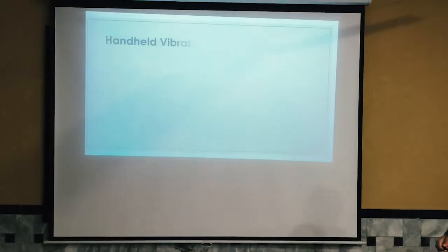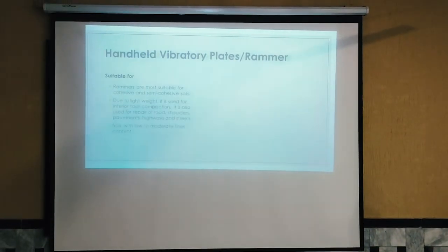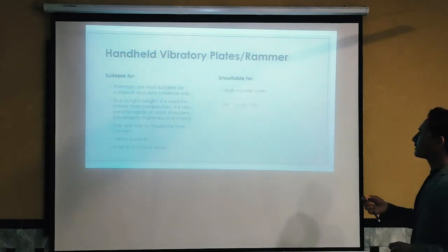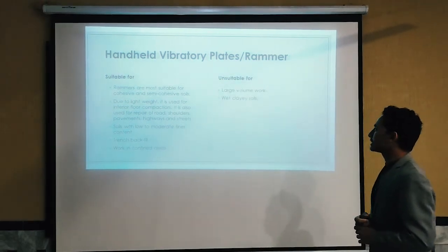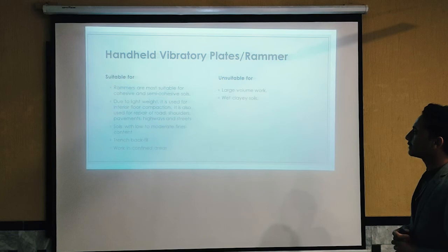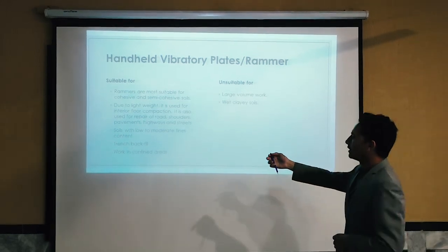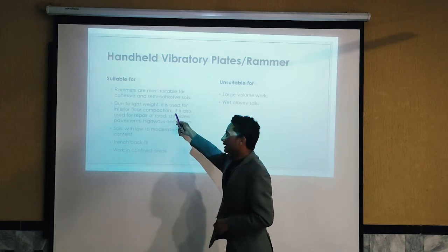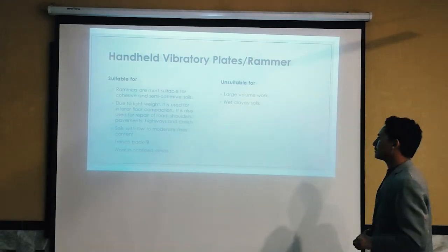Next, please. Rammers are more suitable for cohesive and semi-cohesive soil. Due to their light weight, they are used for interior floor compaction, which I have told you before, that we can use it locally.